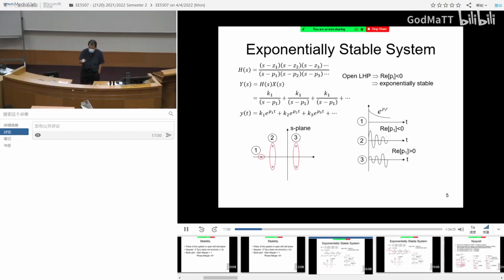not only is there a solution, you can find it. Then I can rewrite the polynomial in all these bracket terms. So the numerator will consist of polynomials like (s minus z1), (s minus z2), (s minus z3), and so on and so forth. In terms of the poles, it will consist of (s minus p1), (s minus p2), (s minus p3). And from mathematics, we know.